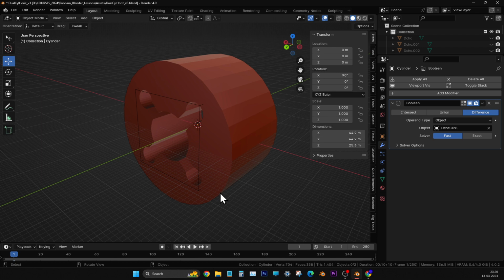We will be applying one more option. Just below that, there is a downward pointing triangle in the properties editor. Yeah, there. Now there is one more remesh. So first we applied the remesh modifier, then we have to apply remesh. Go down, in the settings one. Yeah, that one. So this voxelization we should also apply. For some objects the quadrilateral last option will also be nice, but we can do that only after voxelization. But for this type of shape, the quadrilateral is not working, so we will stop with the voxelization only.